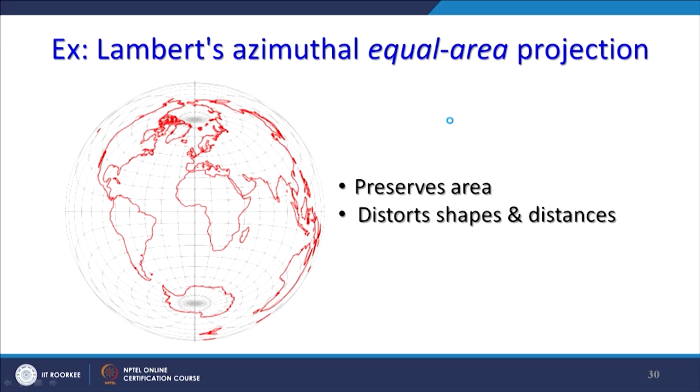What you see in Google Earth has a map projection too, but when you zoom in, the distortions which come because of the curvature of the earth will not be there, and therefore, if you do distance measurements, you are not going to encounter big problems.